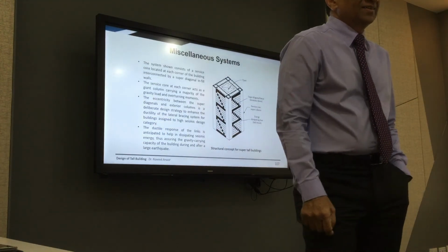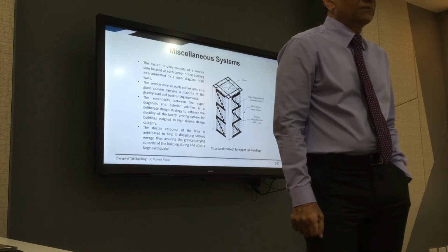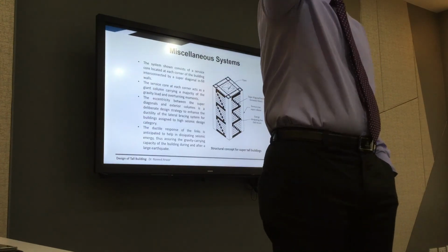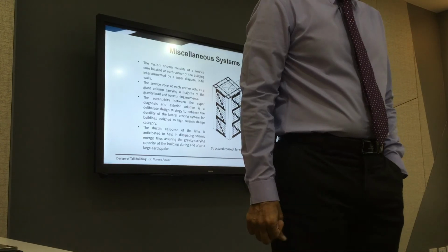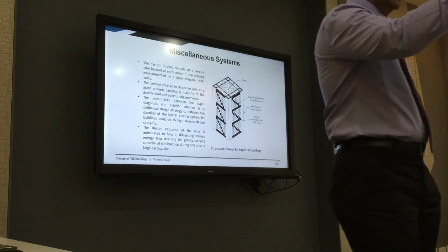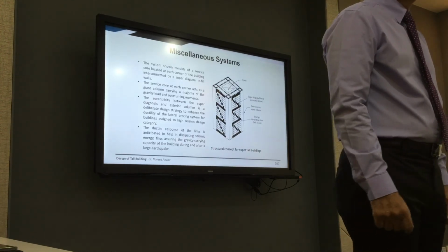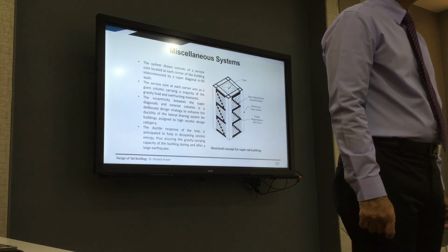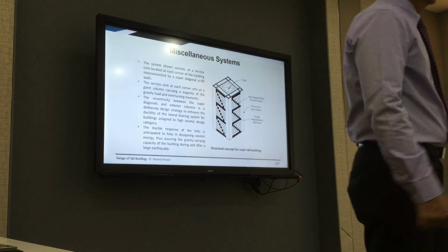I learned about the effect of frame and shear wall interaction, which have different deformation patterns, and also the effect of the outrigger. Okay, next one. The effect of coupling beams in a shear wall is very important to reduce deflection from lateral load. Next one. We learned about the importance of the outrigger effect and how it can help to change the stiffness and get greater efficiency. Okay.